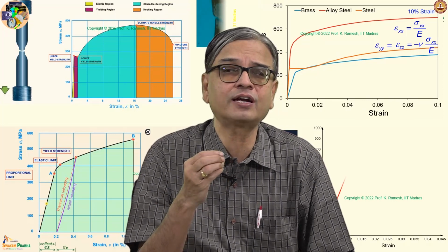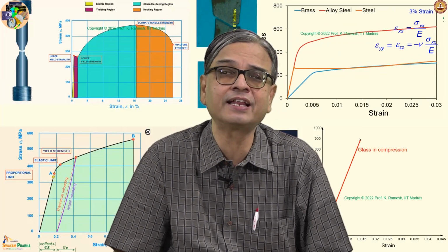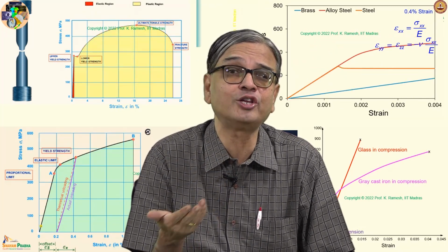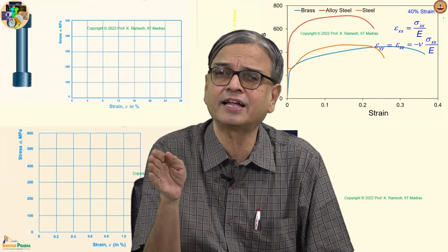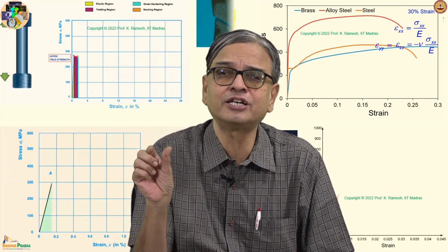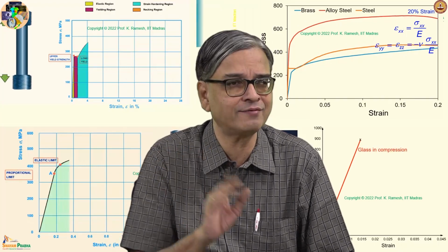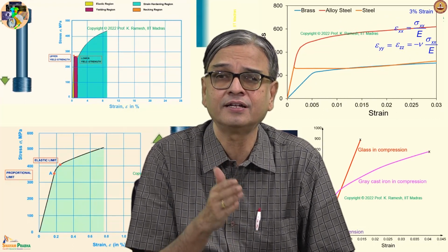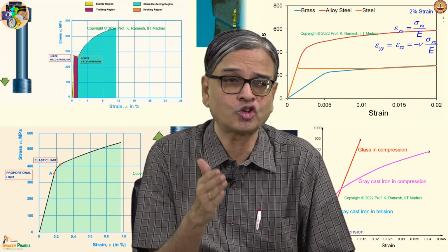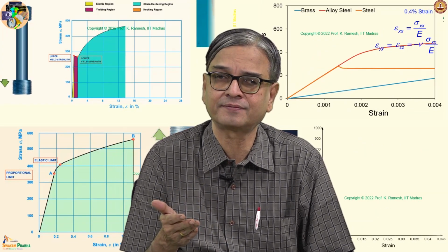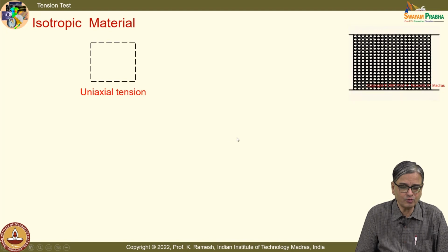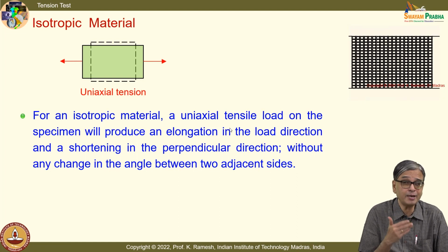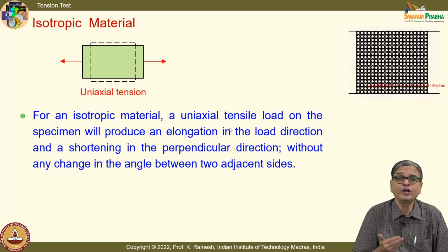If at all I look at what material aspect I bring in, we have said that it is an elastic continuum. That was used because when the limit delta A tends to 0, or the element shrinks to a point, you need to have that idealization. Otherwise, we have not qualified whether it is an isotropic material, or an orthotropic material, or an anisotropic material. Fine. Now, we will look at some of the experimental observations, which also help us to formulate the constitutive laws.